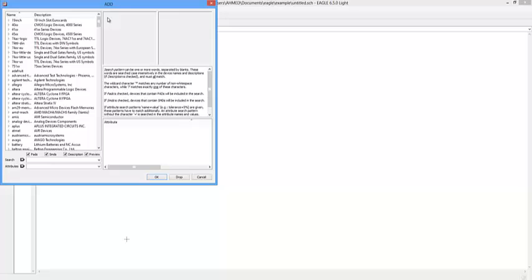Anyway, moving on. So let's say we have a Raspberry Pi, the hobbyist favorite playing toy right now, and we wanted to control two motors, make them rotate to the right or left. So when you say motor direction control, that means H-bridge.